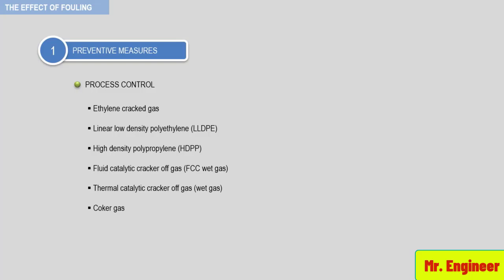The temperature below which fouling can be prevented varies with each process, compressor, and application. Monitoring of process conditions is necessary to establish a threshold temperature in each case. In some cases, however, fouling cannot be prevented with the existing compressor. It may be necessary to modify the aerodynamic design or add additional cooling.